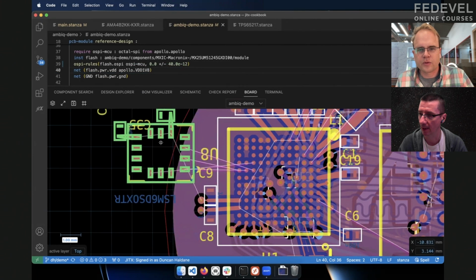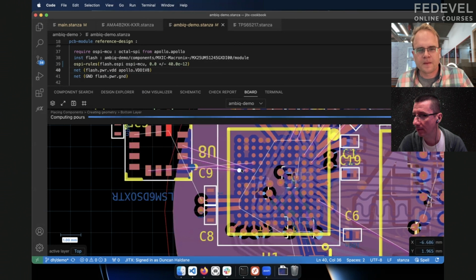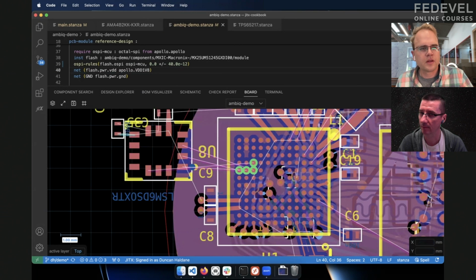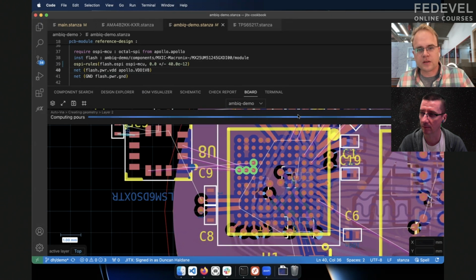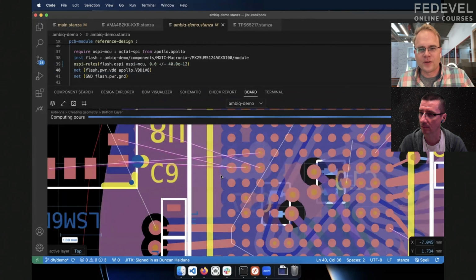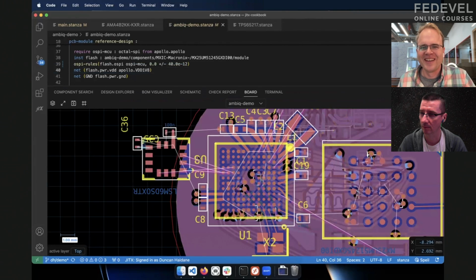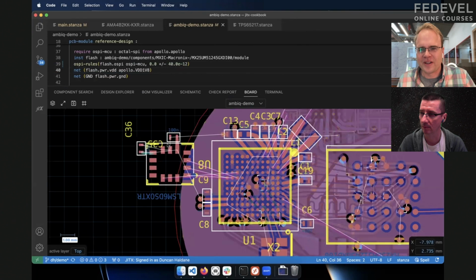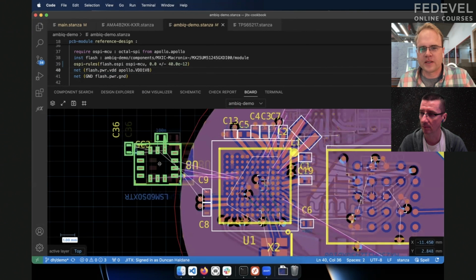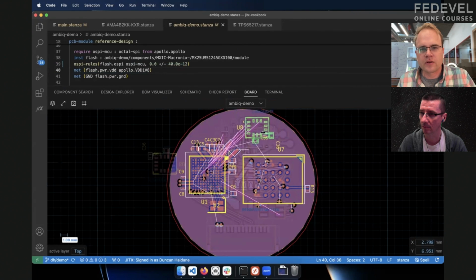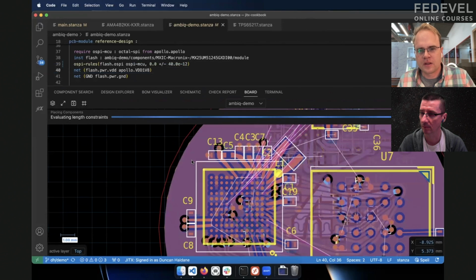Is it those 4? Yes. Pins? All right. 1, 2, 3, 4. And give me a top micro via, shift V. So auto via is helpful. When it's via in pad, it's not a very complicated computation. All right, so then I'll move this in place. Get it over here, looks pretty good.